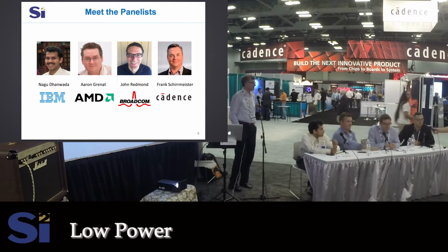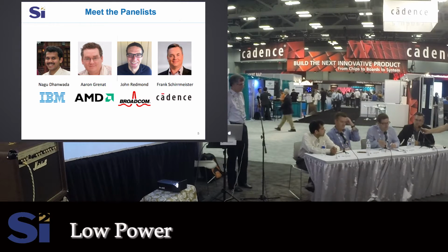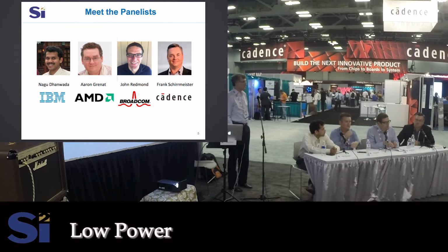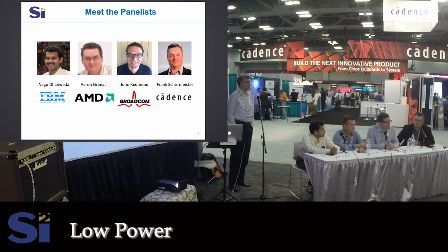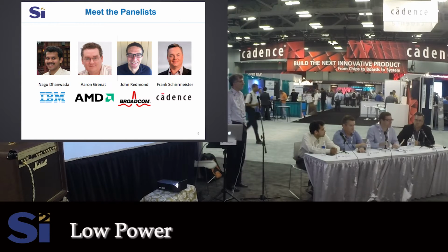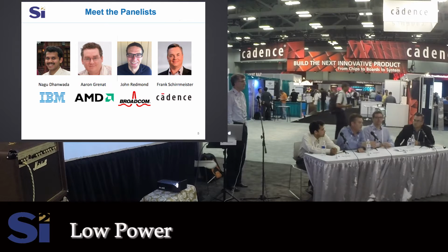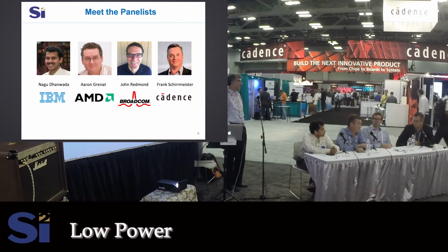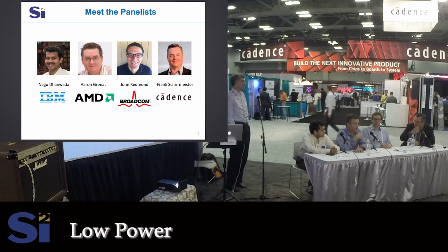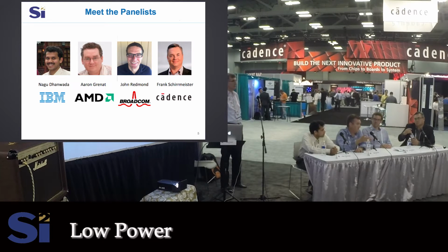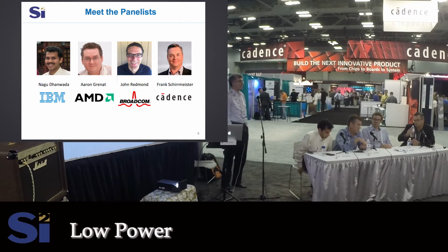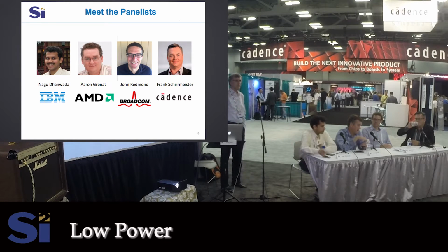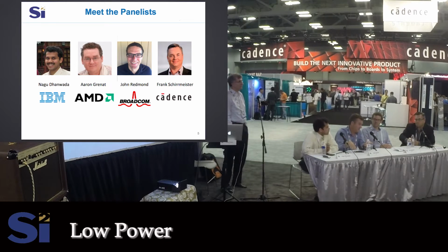So from my perspective, oxides, I mean, we have it, but it's not a problem. Nagu was mentioning 30C deltas. We're not seeing that. So we have it, but it's not a problem. We guard band for it when doing our power calculations and our firmware loops, right? So we know there's a hot spot. And for our reliability limit, we know we have to cap it based on what that hot spot could be versus what we're measuring at our various thermal sensors, right?